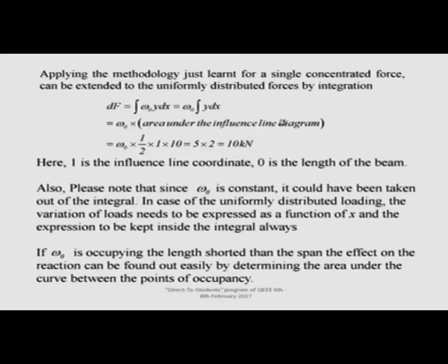It convinces and it proves, and it also gives us confidence that what we did is correct. I am going to extend it further to complicated problems. For the uniformly distributed load, I find the area under the influence line diagram, multiply by the uniformly distributed load and determine the effect. If this load is varying, I will retain it inside the integral and express it as a function, as I have expressed this y, and then I will just do that.